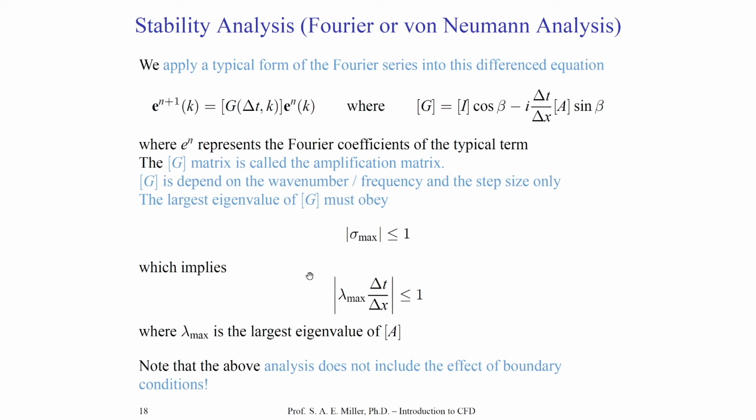This is often a topic, and many boundary condition choices for some solvers might cause the solver to be unstable, where the solver itself is inherently stable in the middle of the domain. Remember, the boundary conditions are actually a set of different partial differential equations, or simplification of them, or even specification of the solution on the boundary with its respective discretization. We would also have to apply some sort of stability analysis to the boundary condition equations, separately from the stability analysis of the numerical scheme that advances it in time within the middle of the domain.